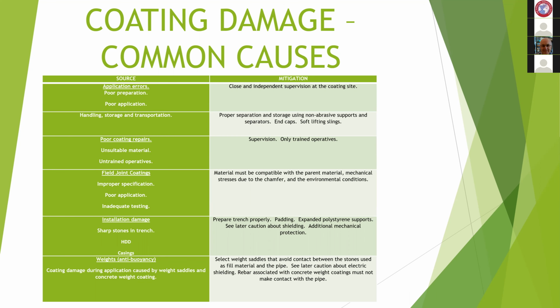Just because water gets in doesn't mean the cathodic protection current will get in. And I'm afraid in the case of disbonded heat shrink sleeves, the solution really is only to keep pigging and keep your fingers crossed, or to expose them one by one and do them properly, which is what you should have done in the first case.